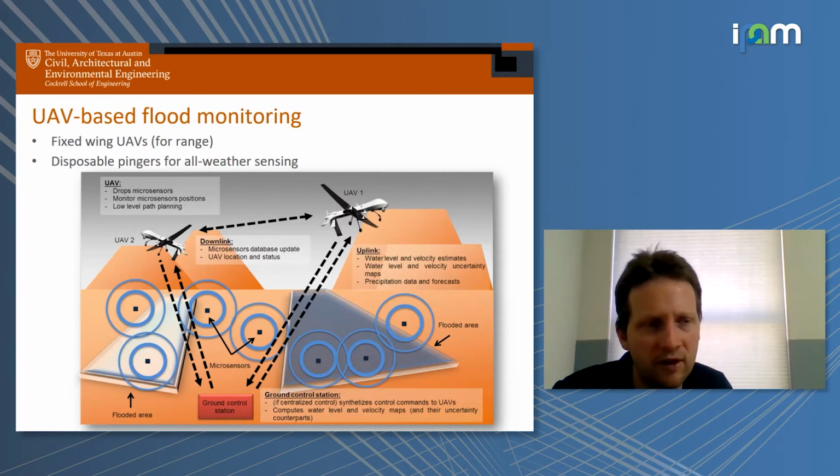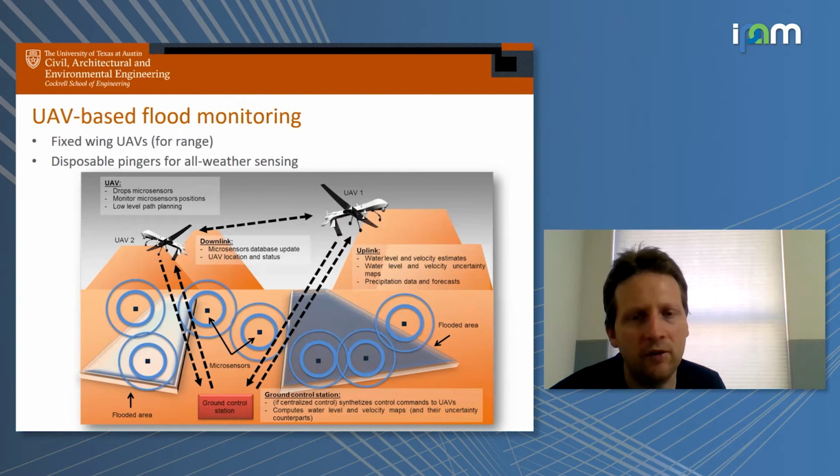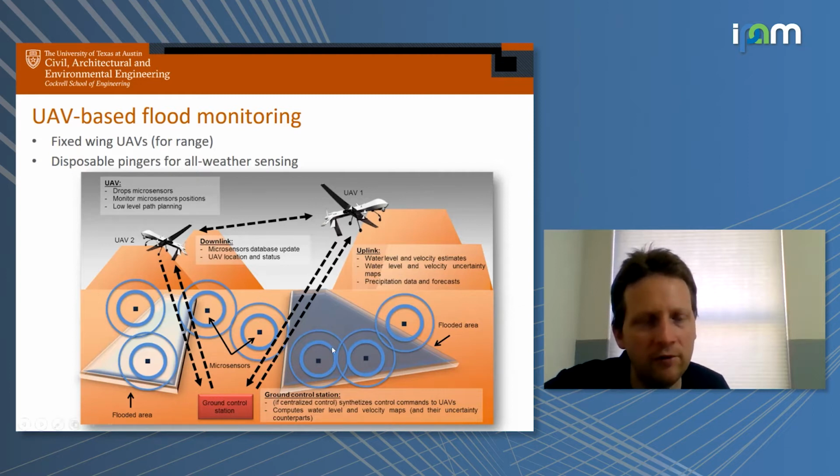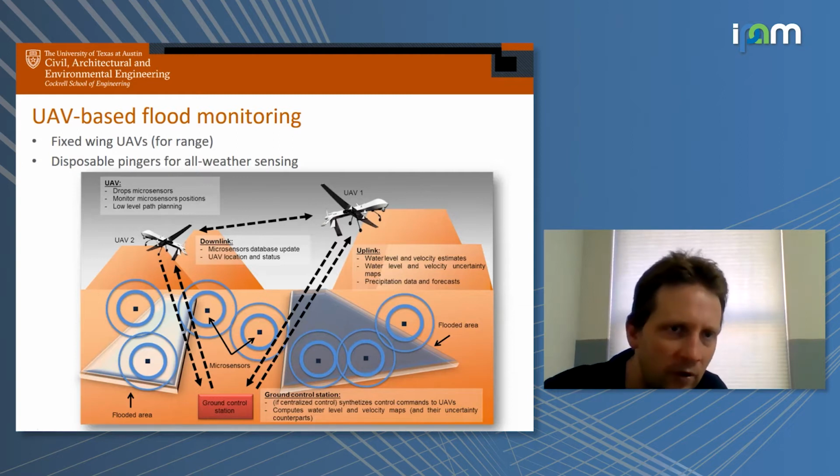So these are radars that can give you the elevation of the ground. So you could use them theoretically to estimate if there is water on the ground and if there are flows, but the reality is that these radars are still too uncertain. They have an uncertainty of about 20 centimeters in height. So that means that you can never be sure that a flood occurs. A flood is dangerous above 10 or 20 centimeters of fast running water. You already have a risk of dying in a flood. So it doesn't need to be a major flood to be dangerous.